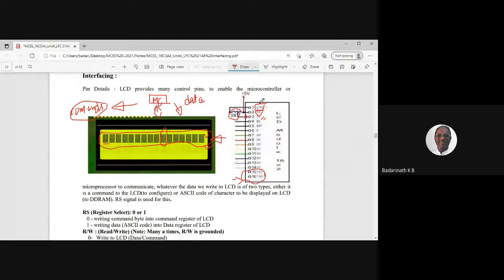So these are the 6 pins related to the power supply. VCC and ground give power to the microcontroller and the logic inside. The LED+ and LED- pins, 15 and 16, enable the backlight for the LCD, and VO, the third pin, is for contrast adjustment.